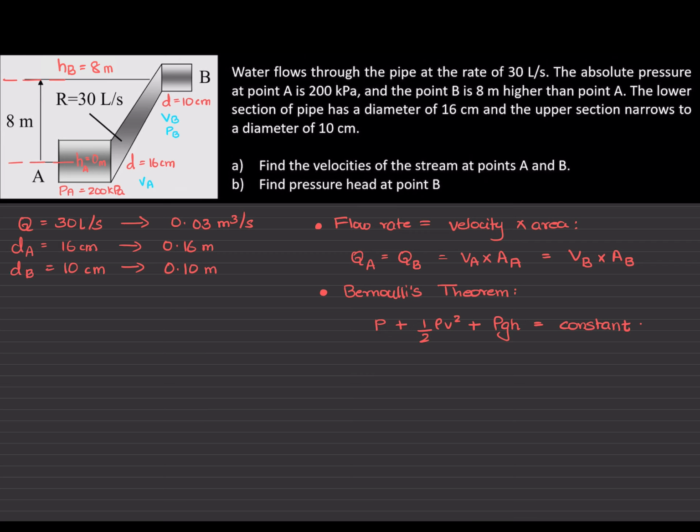In order to work that out, I can use this mass flow rate equation that I've written down in here, as mass flow rate is going to be constant throughout the system. And in order to work that out, we need to work out what is area at A and what is area at B. So cross-sectional area over here and cross-sectional area over there. So area of cross-section A can be found by just using pi r square, which is equal to pi times, we know the diameter divided by 2 will give us the radius, so the whole square, and working that out will give us our answer to be